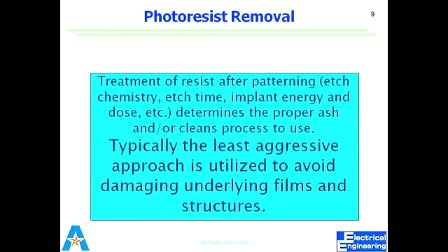Because maybe for etching one material, you may have two to three gases available, but one gas reacts faster than the other. So the etch rate of every gas is different from the other. So these are the three to four parameters you need to keep in mind when working with the dry etching process: the time, the concentration, the etch rate, and the energy or RF power.